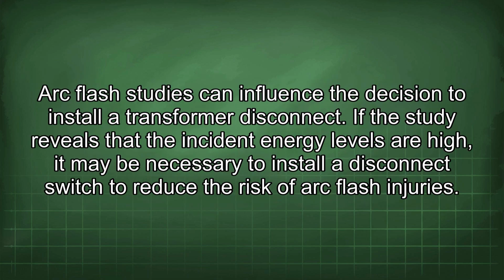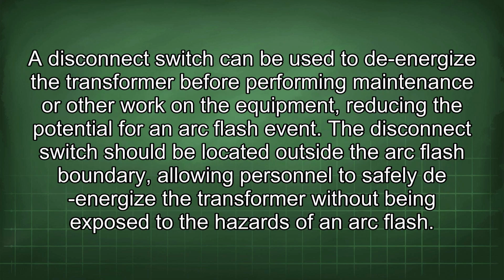Arc flash studies can influence the decision to install a transformer disconnect. If the study reveals that the incident energy levels are high, it may be necessary to install a disconnect switch to reduce the risk of arc flash injuries. A disconnect switch can be used to de-energize the transformer before performing maintenance or other work on the equipment, reducing the potential for an arc flash event. The disconnect switch should be located outside the arc flash boundary, allowing personnel to safely de-energize the transformer without being exposed to the hazards of an arc flash.